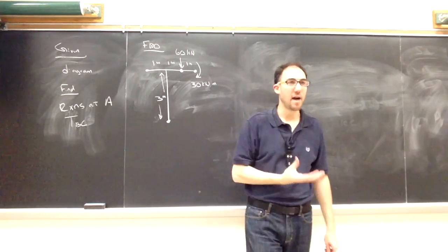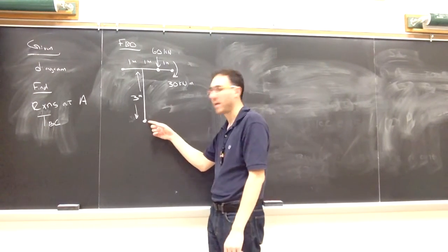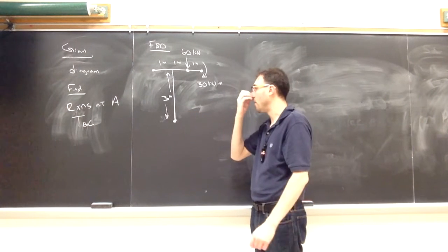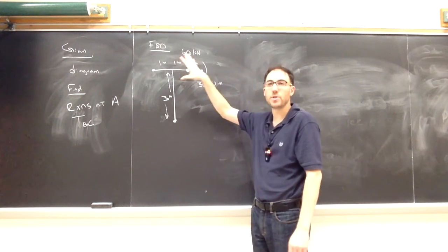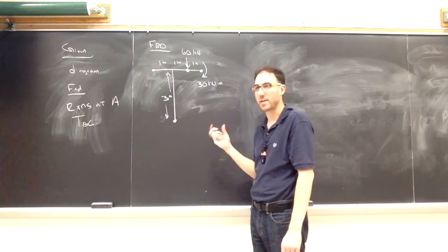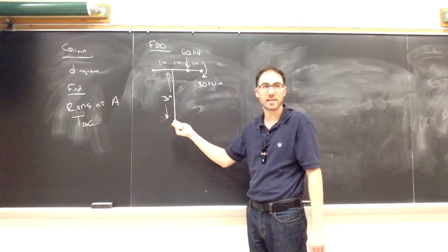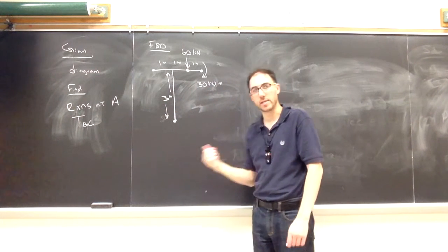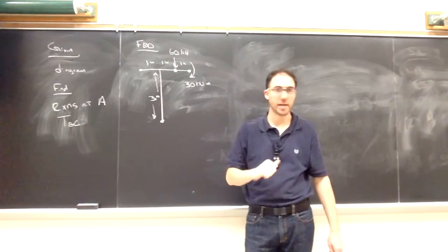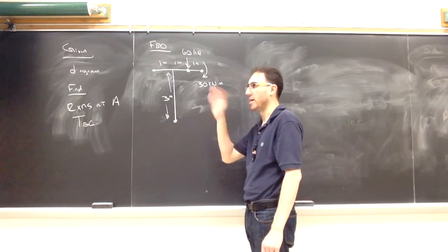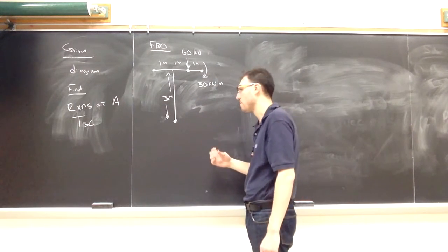But now again, because I did not draw the pin in my picture, I've separated it out. I have to put what the pin did to the object that I kept. So this is a support, it's a pin support. This is where I think, because the pin is there, what does it prevent my object from doing, translation-wise and rotation-wise? Even though it was just on the previous page, we'll go through the thought process here.